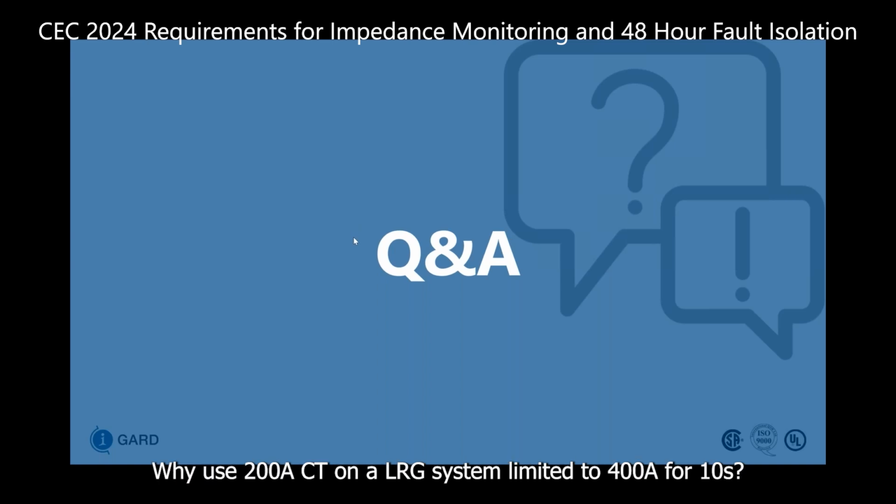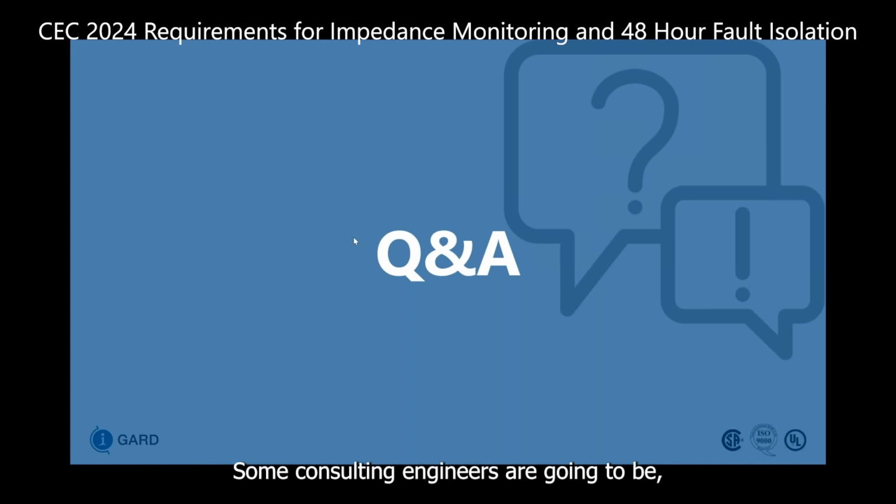Why use a 200 amp CT on an LRG system limited to 400 amps for 10 seconds? Some consulting engineers are going to be tripping their system upon 20% detection in a 400 amp system. That would be about 80 amps. In that case, they may not need the full 400 to 5 CT, since their trip range is 20% of the resistor's rating. Some people use 50%, some people use 25%.